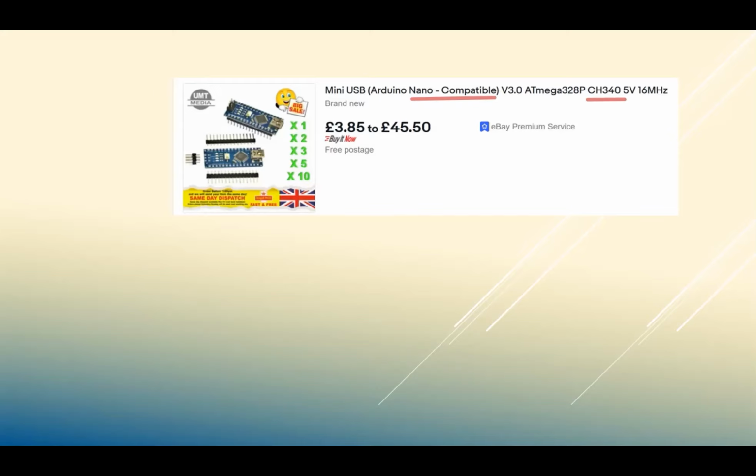It's got a CH340, which is a chip that is cheaper than the ones used in the official Nanos, and therefore is very common in compatibles. Everything else in there works on 5 volts, 16 megahertz, as per the spec. So although it says a lot, there's no mystery there.